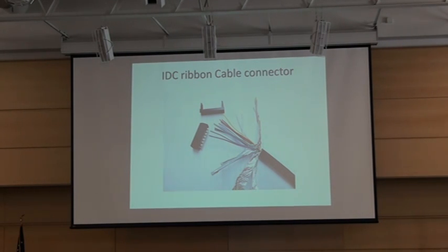a typical cable produced by Whitney Blake, and it's got all sorts of parts. The most important is the wires here, the individual conductors that transmit the signals. Also, we have some drain wires here, which are ground for grounding equipment, so that it's all the same level. And that in this picture is just kind of wound into the shielding that normally would wrap all this up. We have some cotton in there for shape, and then also some nice foil here for shielding. So as you can see, we have a nice round connector right here, or round cable, excuse me.